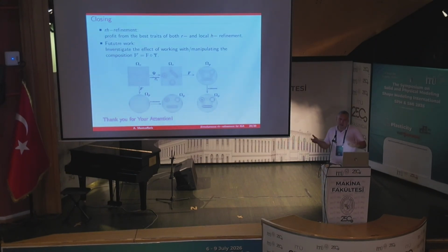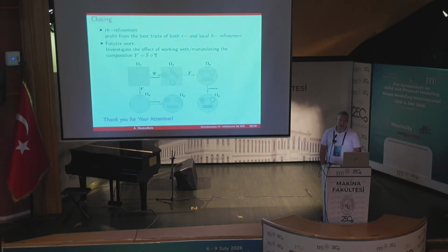You can imagine in an unstructured mesh, you cannot play this trick, so you have to solve another PDE before solving your PDE to get the mesh. And maybe also, of course, there are always problems with bijection. Maybe in some cases you don't get bijectivity. Yeah, maybe there are all these things to consider. So to say, it's an advanced remeshing method, so it comes with all the problems of that, for sure.